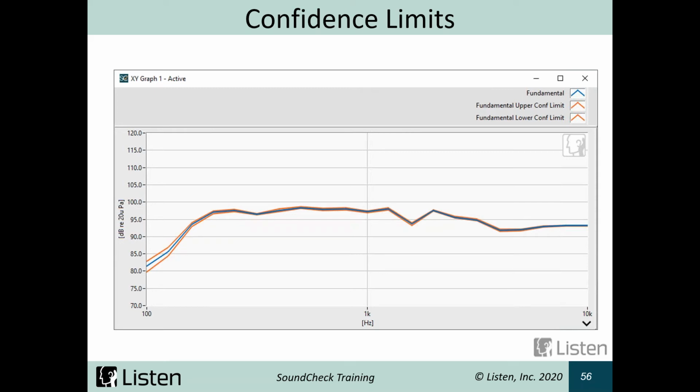One thing to note here is the low end, though. Even though most of my signal is pretty close, something you can often see is where my device isn't outputting a lot of signal because I might be rolling off. No matter how long I sweep there, no matter how close I am to my device, I'm not going to get a lot of confidence there just because my device isn't outputting a lot of signal.